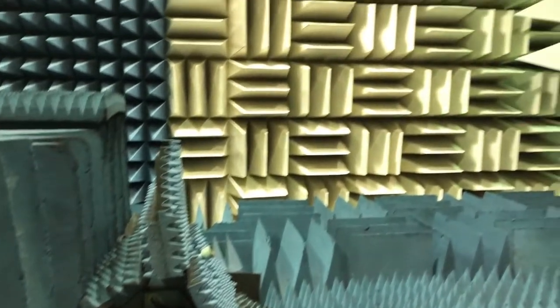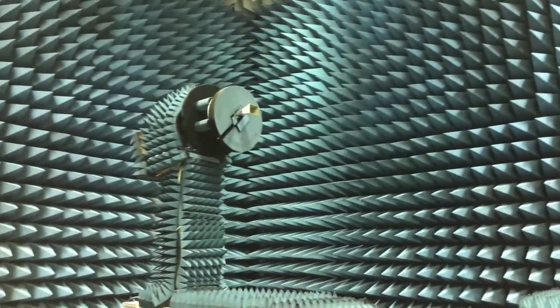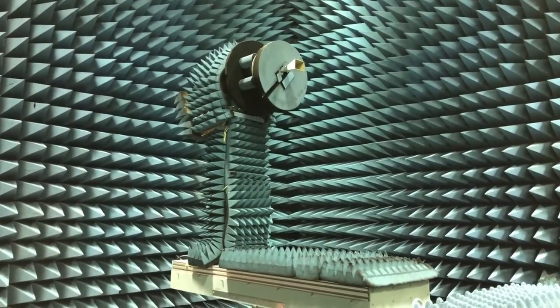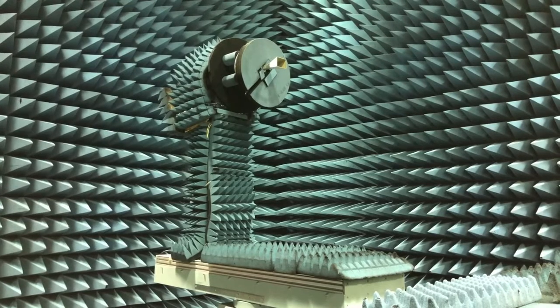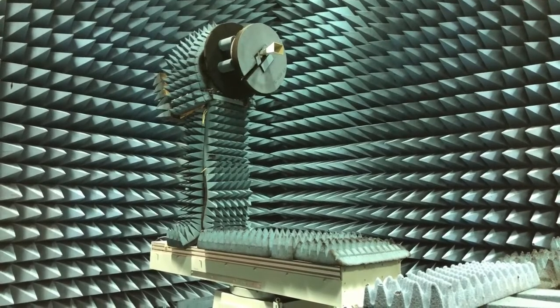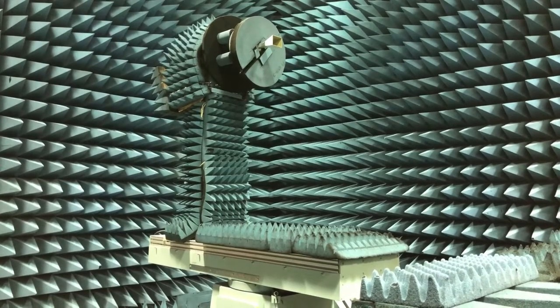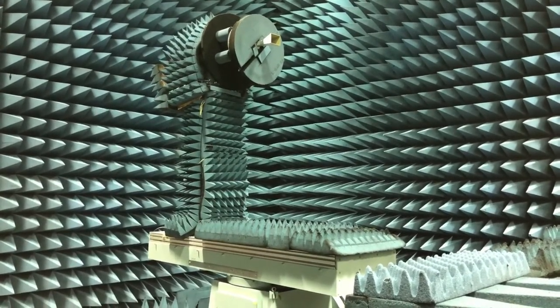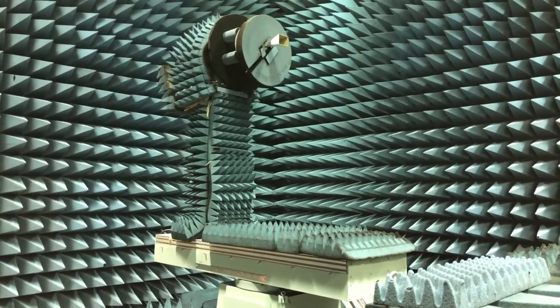And when the feed rotates 90 degrees, essentially the polarization of the field that's coming out of the reflector is going to change. And during filming, I'm going to be focusing on the antenna under test, which is a horn antenna mounted on the tower. Right now, it is mounted at 0°. And in the measurements, we're going to be performing measurements at different angles. The starting angle is -90 to +90. So we're going to be starting the measurement, and you can take a look at what's going to be the measurement.